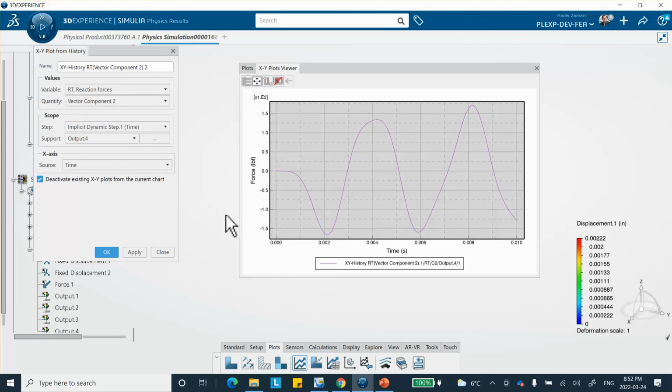And again, this makes sense because as time builds up, the load is pulling this thing to the right. Reaction force is going to be negative. Okay. And by the way, notice that these are roughly the same numbers that we got when I did modal dynamics. So we have solved this problem with modal dynamics, and in this tutorial we solved it with implicit dynamics. That is it.